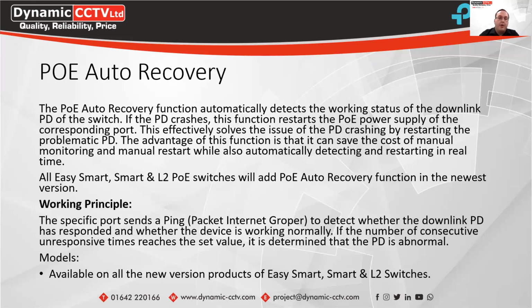So the PoE Auto Recovery, if the PD crashes, the PoE switch will automatically restart the PoE power supply for the corresponding port, which basically creates a reboot on the camera, which is an automatic detection which you can configure through the web front end of the camera itself. So the way this works is it will send out a ping to detect whether or not the downlink on that port has responded, where the device is working normally.